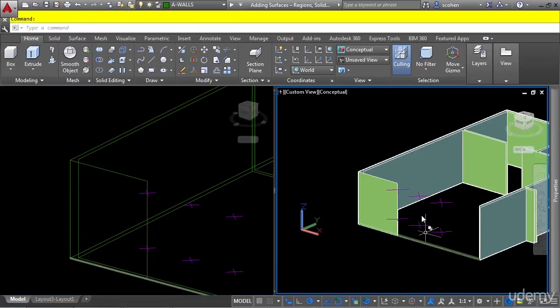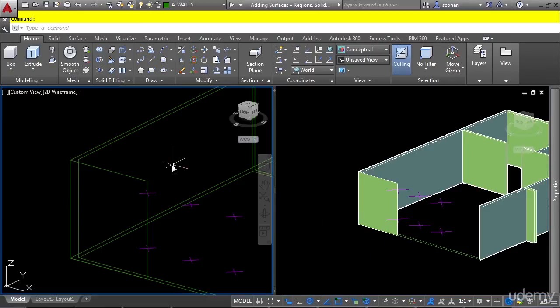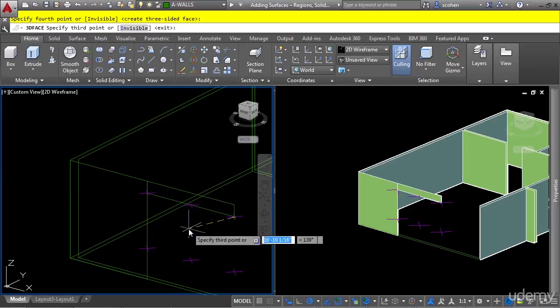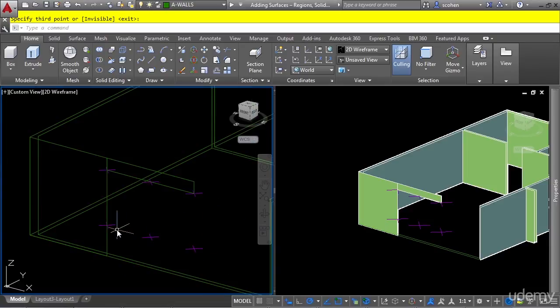Again, as you can see, it's showing up in the shaded view. Press enter to repeat the command. And now complete the window by simply acquiring and tracking the correct points. Notice how you only have to do 3, as this is all that's required to complete the 3D face. Again, just using O-tracking to acquire the different points and intersections.